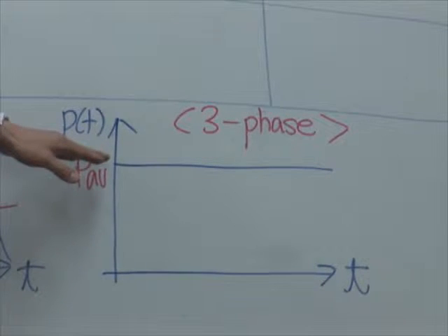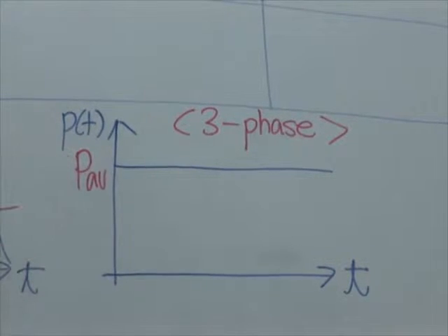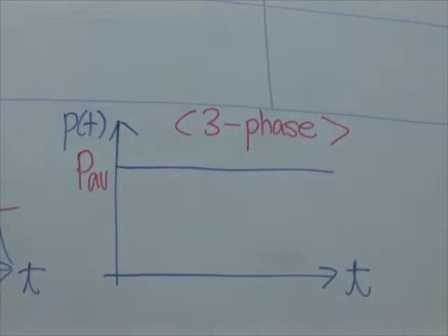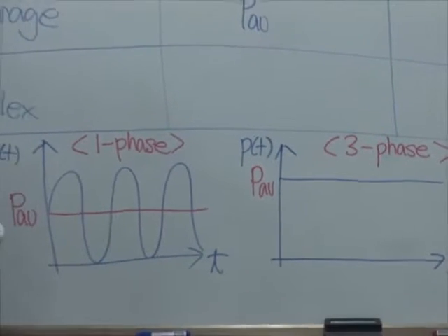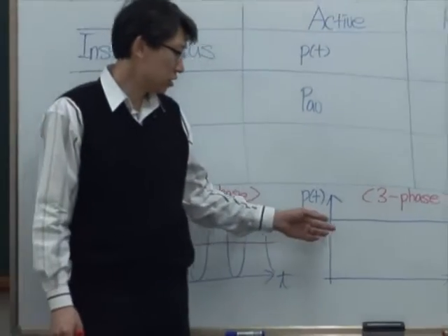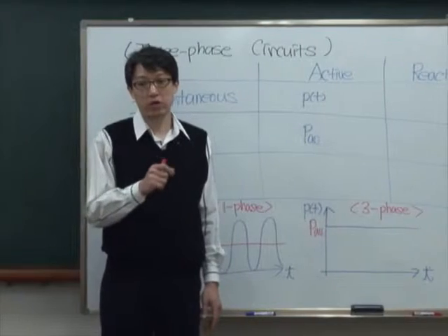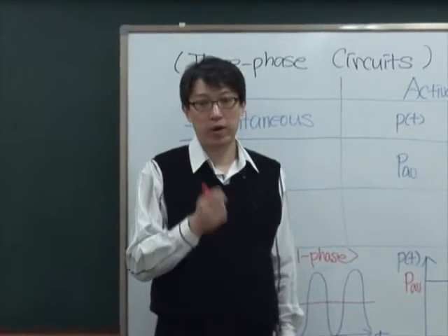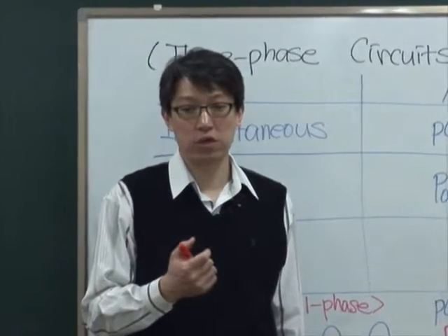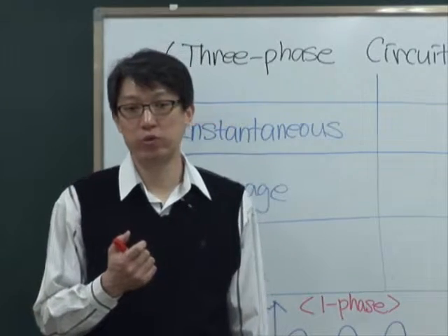It has the same value as average power. Right? This is amazing, right? This is amazing. So once you hook up this induction motor to three-phase case, the power doesn't have oscillation, which means we can transform the power concept into torque, okay? Because power is equal to torque times speed. So when there is no ripple on power, that means there is no ripple on torque.